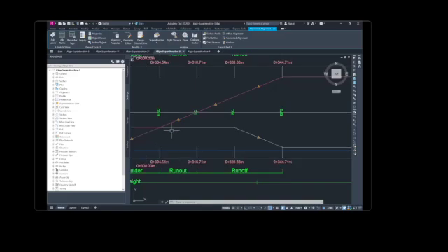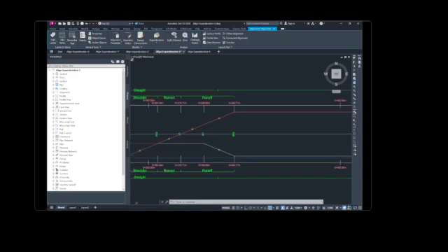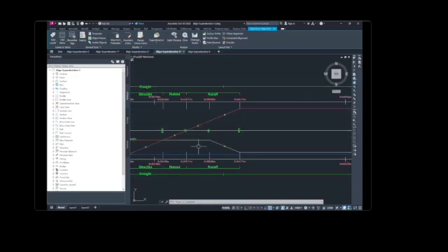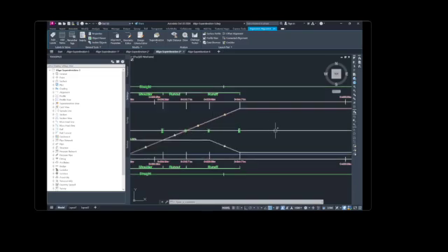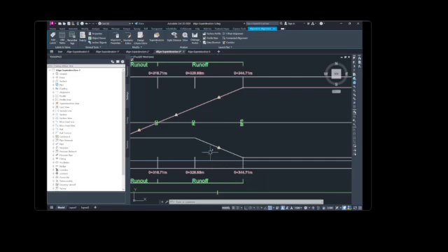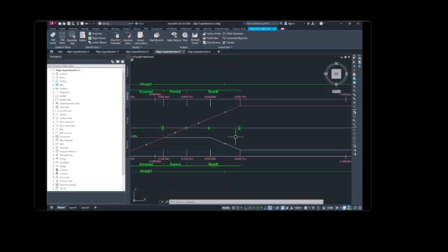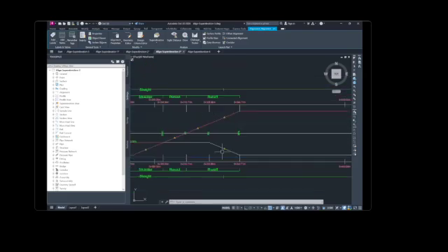At station 0 plus 304.54, the left lane dark red starts to transition from the normal minus 2% slope. At station 0 plus 316.71, the left lane and shoulder area are at 0% slope. And at station 0 plus 328.8, the right lane dark blue starts to transition from the normal negative 2% slope.